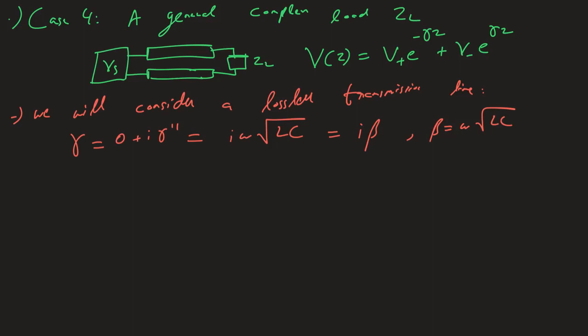So if I write it like that, then I can write my expression for V of z as V of z becomes equal to V plus e to the minus iota beta z plus V minus e to the plus iota beta z. Honestly, the reason for now talking in terms of this real number beta and having an iota there explicitly rather than implicitly is because hyperbolics are best avoided whenever I want you to understand something. So let's just work with normal trigonometric sines and cosines. Otherwise we'll get hyperbolic functions when we add them.